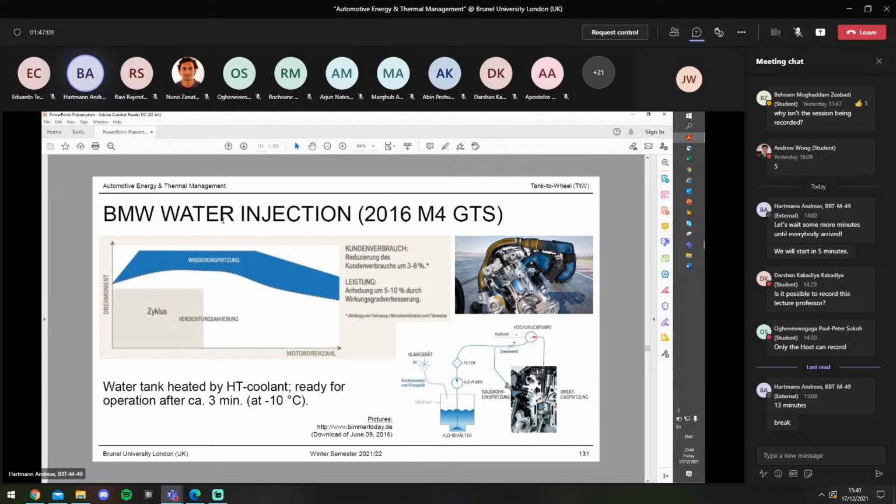And which advantage does such a cool down of the inner temperatures of the combustion chamber provide? The durability of the engine. Yeah, as mentioned several times, one major issue of the combustion is the so-called self-ignition. So we already know that when increasing the compression ratio, uncontrolled self-ignition may occur, but only at very, very high loads.